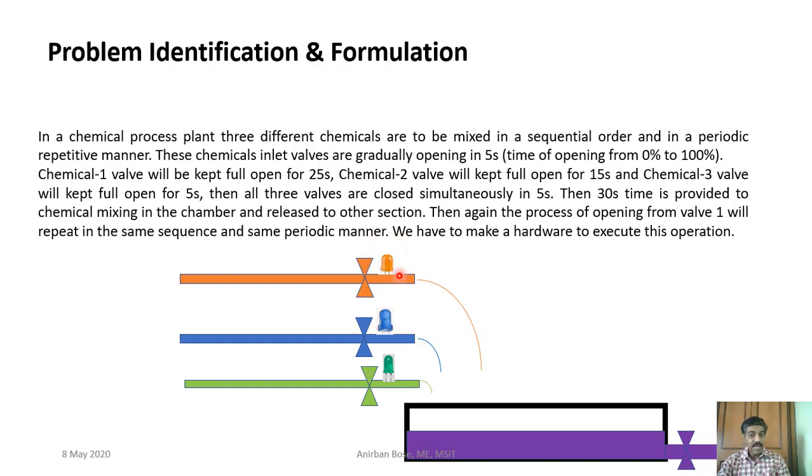The main idea is how we can control the voltage given to this LED so that it will glow from off, gradually increase and ultimately reach full glow, or keep at that full glow for a certain period, and when it closes, its brightness will gradually decrease and finally it will go off. This kind of voltage control we have to give from the Arduino board.